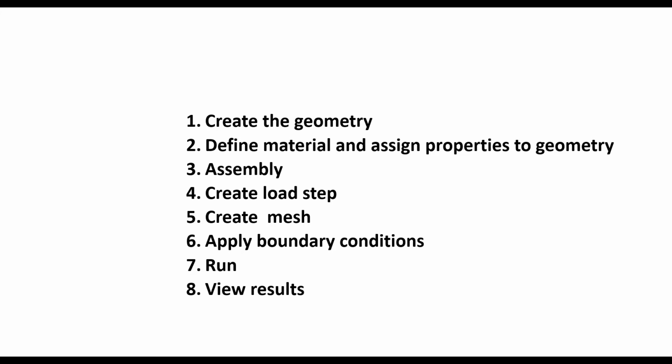Firstly, we create the geometry. Then we define the material and we assign the properties to the geometry. Then we use the assembly function. This feature only exists in Abaqus.